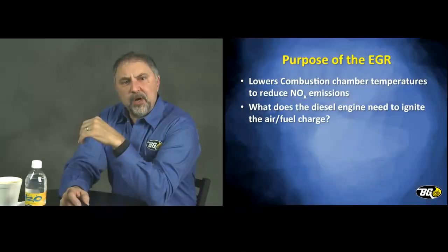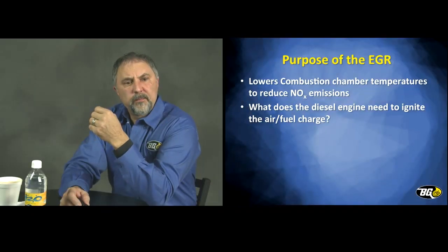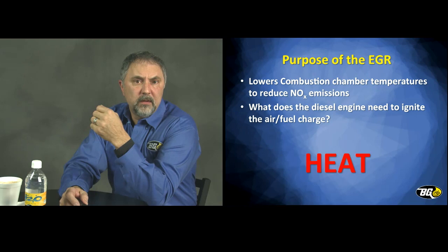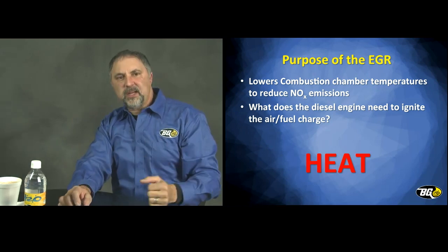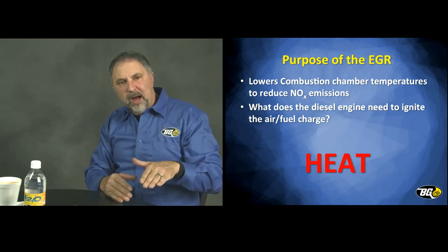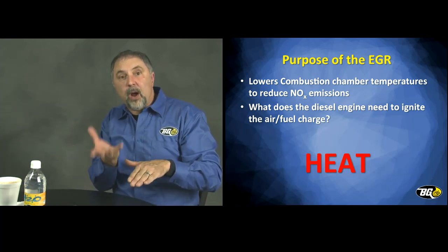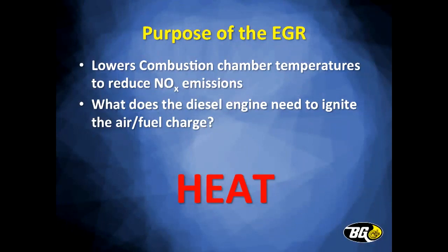Now, what does a diesel engine need to ignite the air fuel charge? It doesn't have a spark plug. Heat. And the heat's done through compression. So to me, in my mind's eye, or any diesel tech that's out there will tell you, well, if I'm trying to cool the combustion chambers off, but I need the heat from the combustion chamber to ignite the air fuel charge, it's like having a campfire, you start sprinkling water on it. So all your wood doesn't burn. That's soot that starts to head out the tailpipe. But it's something that's required for NOx emissions or soot, so there's this delicate balance going on in the engine.